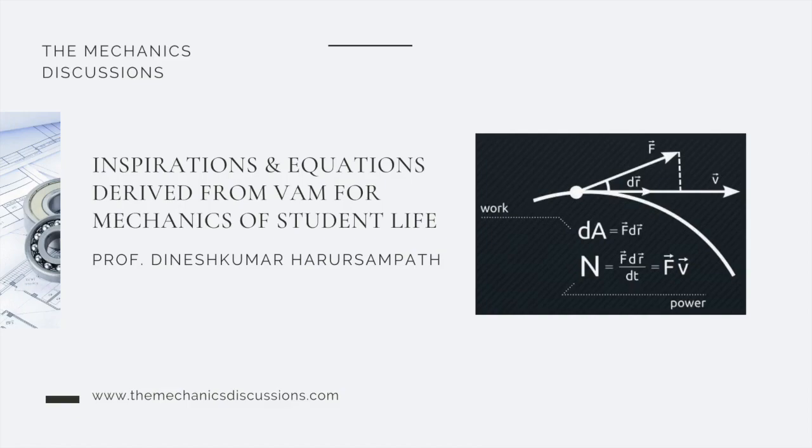So we need to go to the functional, which is prior to the Navier-Stokes equation, or put the Navier-Stokes equation, which is basically a differential form, into an integral form, and that's where we can start applying these. And again, because of the involvement of shear and the boundary layers, there are certain irreversible processes involved, and therefore you may not have an exact variational principle. You might have to go for an approximate variational principle, which can then be governed by the asymptotics.